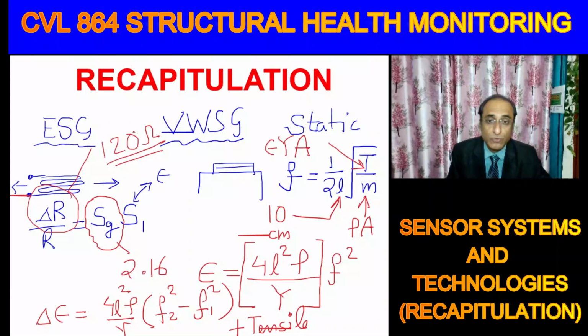But if you see the video, which has been uploaded, you will be able to find the exact value. So 120 is the standard value, but the actual will be something with decimal places also. That is the initial value R0. If you subject it to tension, the value will increase. If you subject the specimen to compression, the value will go down.